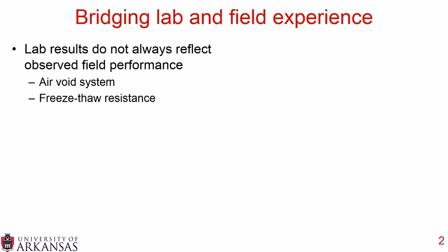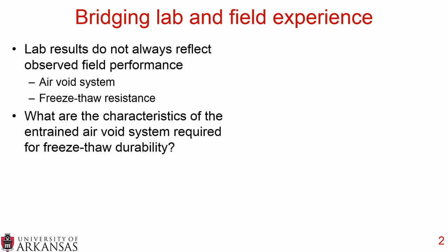of concrete pavements, especially when thinking about the air void system within concrete pavements and the freeze-thaw resistance of concrete pavements. So their key question was, what are the characteristics of the entrained air void system required for freeze-thaw durability?